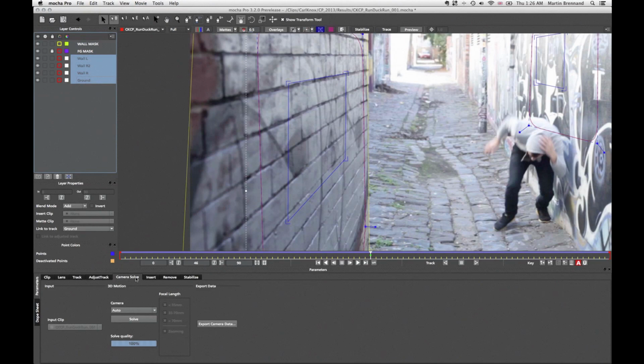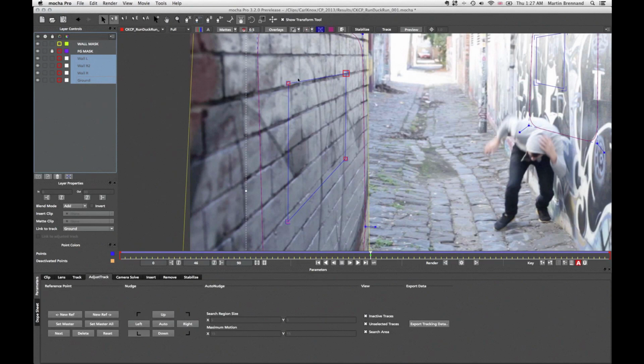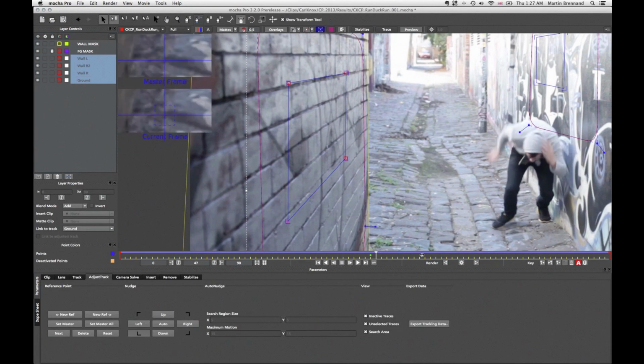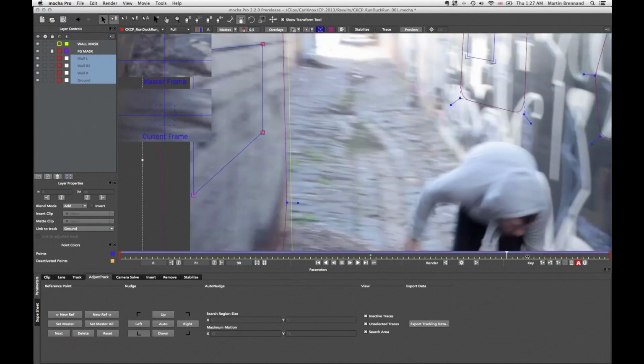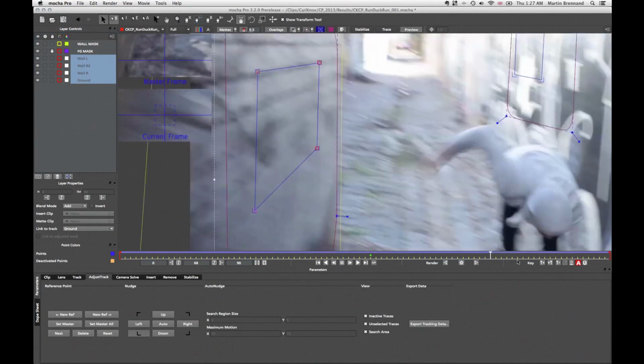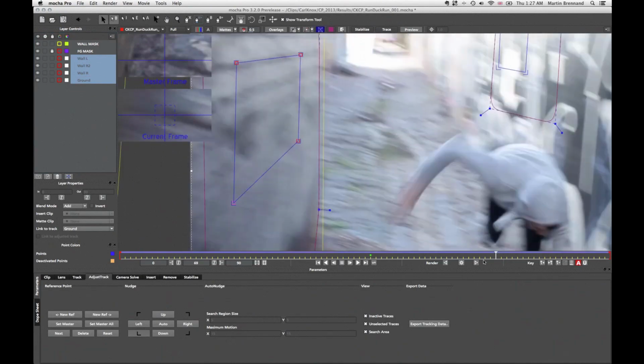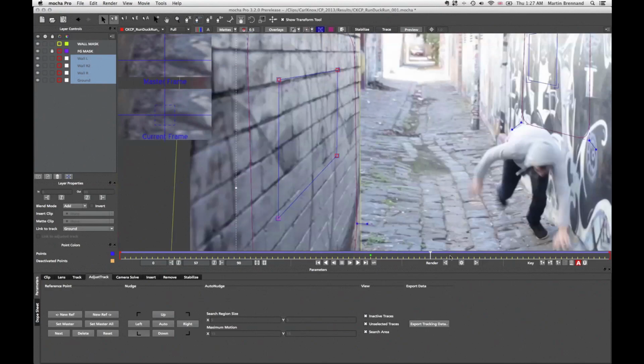And again, just to recap that little workflow, the adjust track module is really used to compensate for tracks that are not perfect, that are drifting, or maybe you want to use these tools to visually look at an offset track with those corner points. And so every surface track that you're going to use for a camera solve would have to be adjust tracked on its own if you needed to. That's right, yeah. You wouldn't select every layer and adjust them all at once.